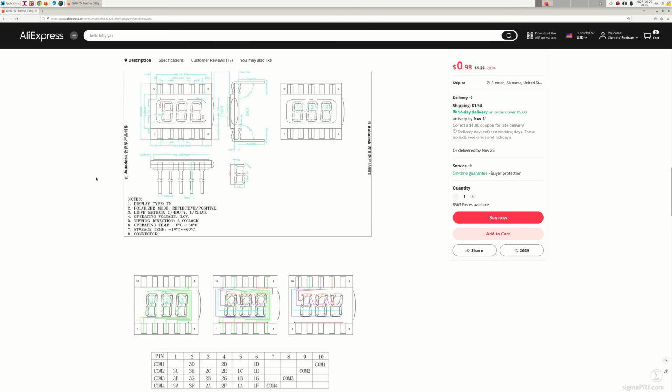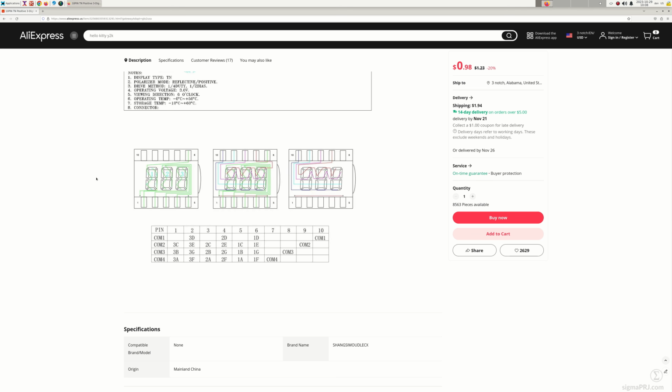Duty cycle will give overall sense in terms of how long each LCD segment will be ignited. In case of 1 quarter, each segment will be activated only 25% of the time. This will allow one single pin to drive 4 segments, where each of the segments will be on for just 1/4 of the duty period. Like here, pin number 6 can drive 1D, 1E, 1G and 1F segments. This can be achieved by having 4 separate command lines, where each of them will have special modulation, which will act like a multiplexer switch, enabling specific segment to be active on just 25% of the time.